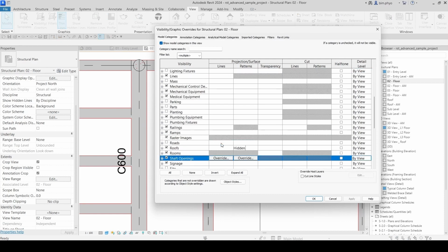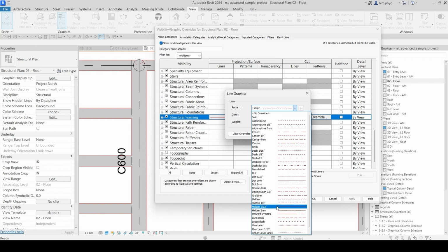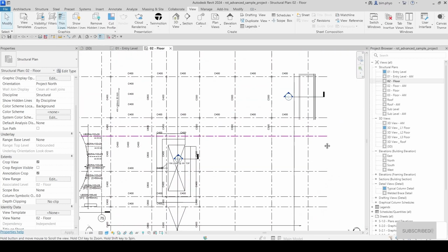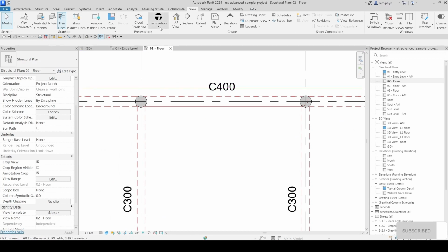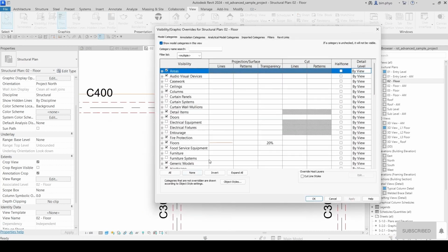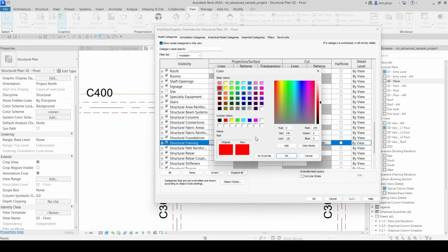The line, special framing, is hidden line. And I might use this one and the transparent one. I will use 20. Look at this. The color is a red color for the beam, orange color for the other. I think the color is a little bit much, so I will choose another color for the beam, special framing. A little bit brighter. This one.